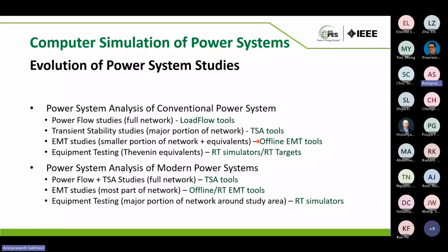And when it comes to equipment testing, a major portion of the network around the study area is now being modeled, because this is the experience that we got from the industry at present. They model a fairly large network around the point where they want to connect any inverter-based generation or HVDC. For that purpose, real-time simulators are being used.